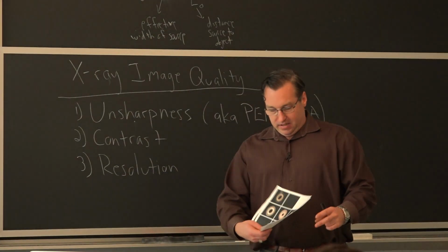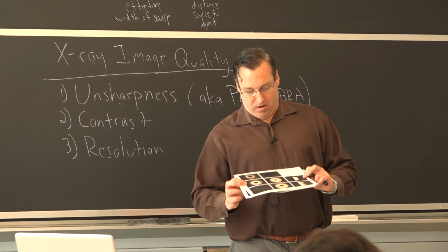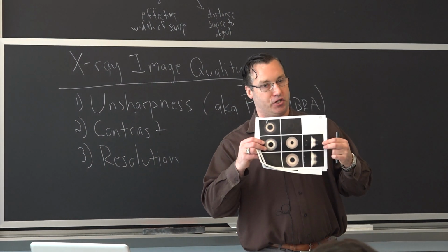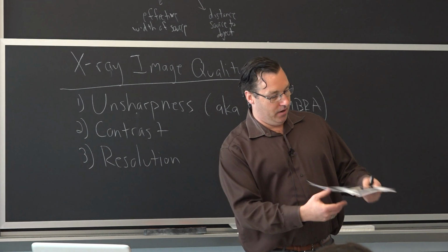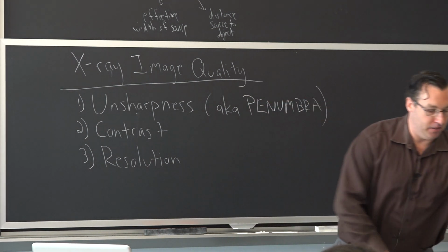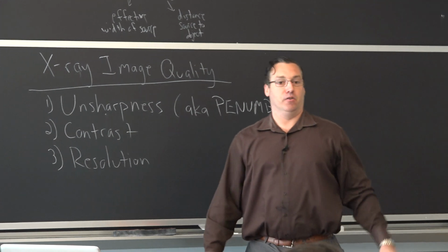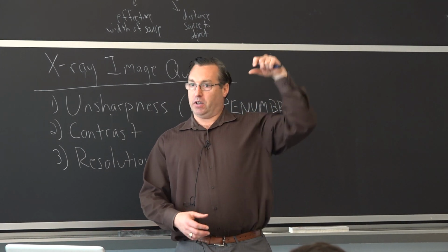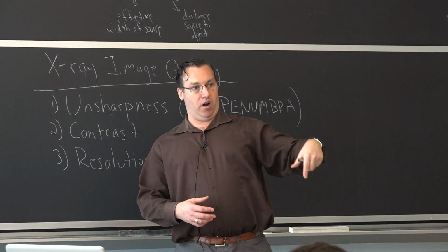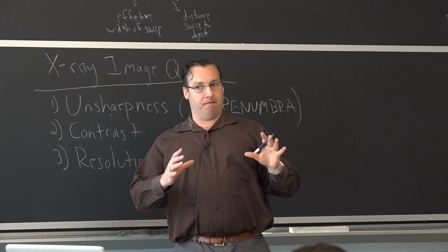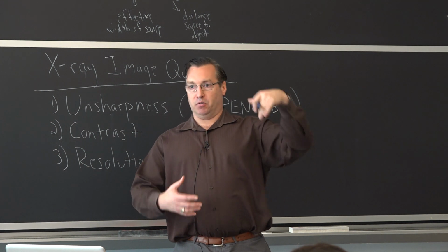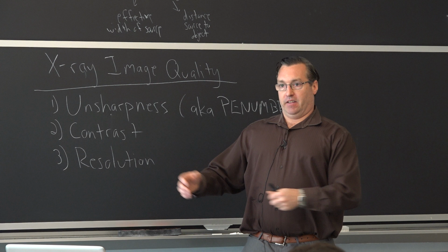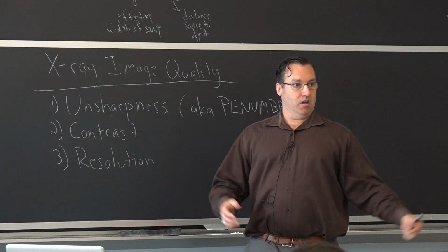So the last thing is, this is what you'll see. This is what I'm talking about, the noise in film radiography. This is from the traditional film, and you'll see that compared to the digital radiography, there's a lot more noise in those images, because it's just a single shot. So if you don't get the accelerating voltage correct, or if you don't have all your variables correct, you just have to redo it again, and that film becomes useless.